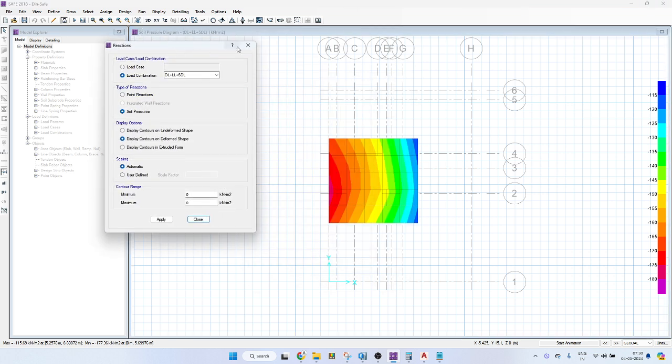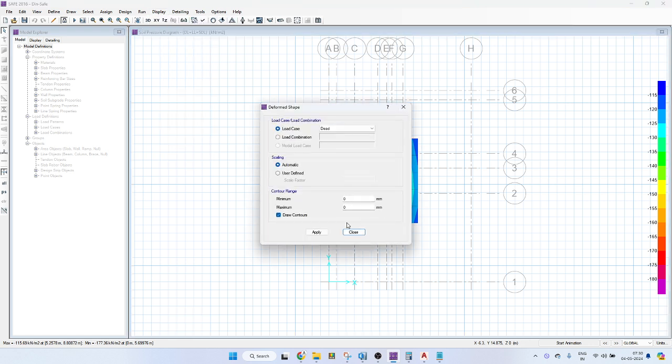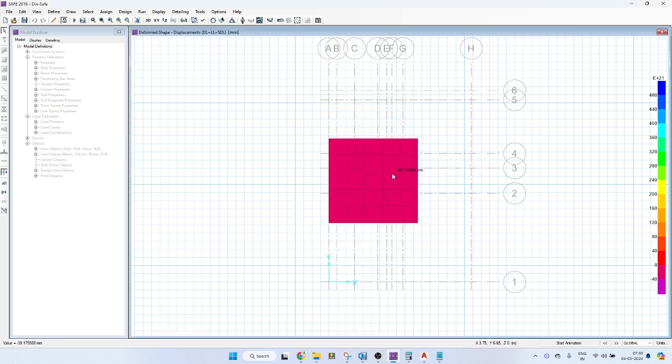So what did we learn? We learned that in load combination, we are checking for load combination without factor of safety. And this deflection should be within 50. To achieve that, we can either increase the size of the footing. If it is not possible, then increase the depth. I increase now by 2 feet.